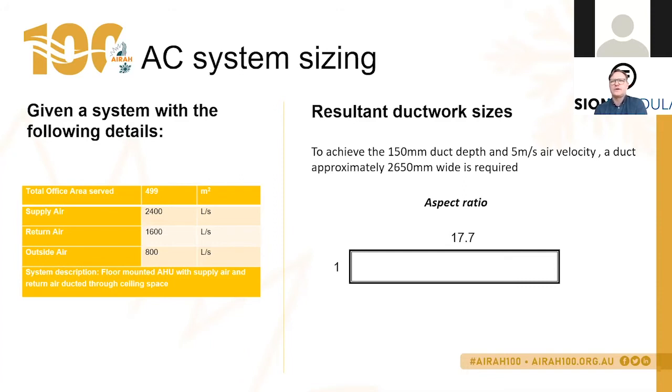You will require additional hangers in the mid portion of the duct, typically because 2,650 millimetres in width is not really self-supporting because ductwork is sheet metal, and you'll need additional supports on the duct and additional hangers. And with ductwork of that width, it can sag or bend in the middle and create low spots.